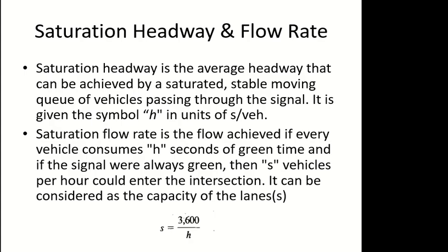The basic relationship is that flow rate is the inverse of headway. So saturation flow rate is the inverse of saturation headway. And because they have different units, I need 3600 here to convert it to per hour.